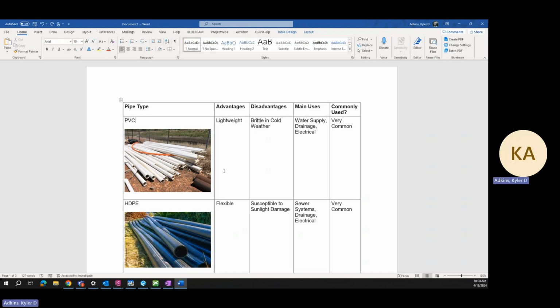Being able to heat up the conduit, you can essentially use heat bending methods. Some utilities use this, and you can heat up the conduit and bend it to whatever angle you need. With large power cables, obviously you have a min and max diameter. You still want to abide by codes and regulations on what type of radius you're using there.